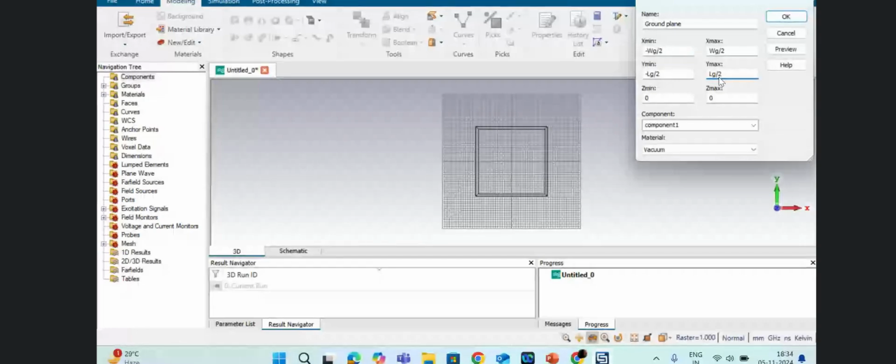So the reference plane, I just took it as 0. I'm going to construct a ground plane on the reference plane. The thickness of the ground plane is 0.035 mm, so I'm going to give T as the thickness. Okay. Any doubt? Shweta, can you mute, please? Thank you. Fine. So T is the thickness of the ground plane.